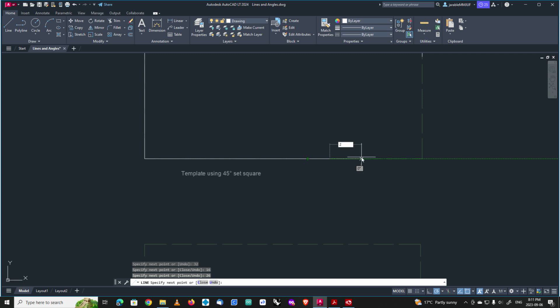Let's say I make a mistake, by the way. Let's say I type in 28. Oh, okay. I'm going to press enter. That went too far. This is the last line segment I created. I typed in the wrong distance. Now I can do one of two things. Of course, I can delete that, or I can press Control Z. Now notice Control Z got rid of that entire line, so the entire sequence I just did. So I really probably could have just deleted that last little segment.